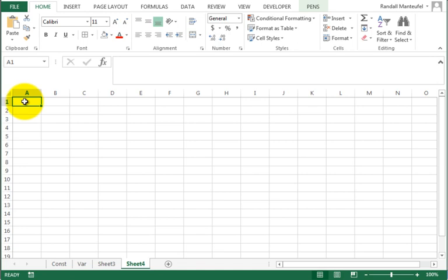So let's go to Excel. This is my way of solving this type of problem. I like to type a comment in cell A1, so it's gas refrigeration with air as a working fluid. Good enough. And then we're going to put a table of properties, but I like to put some of the inputs up front. I know I'm going to use the pressure ratio. And for this problem, the pressure ratio is 2. That's not a lot of boost across the compressor, but it's enough to accomplish refrigeration.